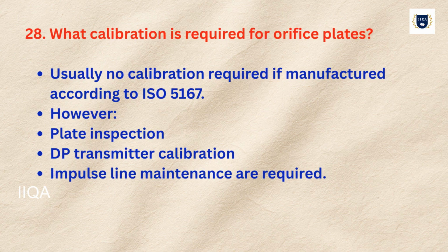What calibration is required for orifice plates? Usually no calibration required if manufactured according to ISO 5167. However, plate inspection, DP transmitter calibration, impulse line maintenance are required.